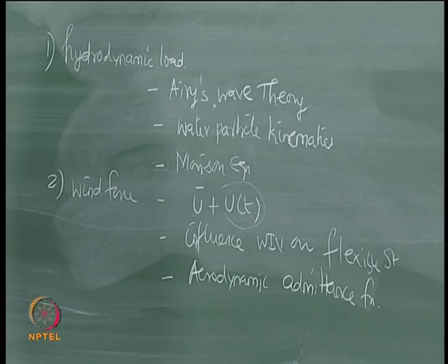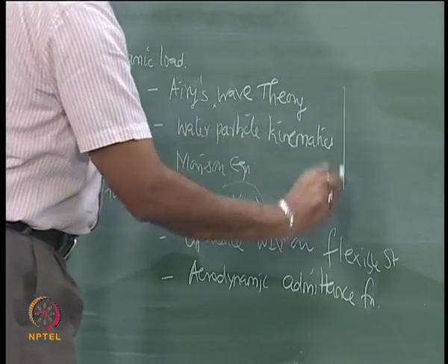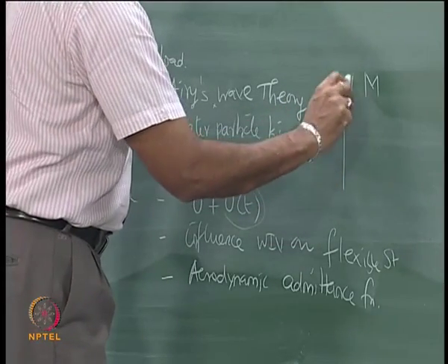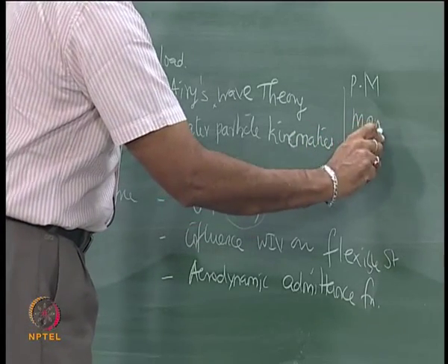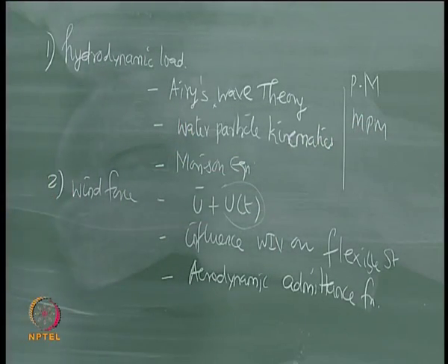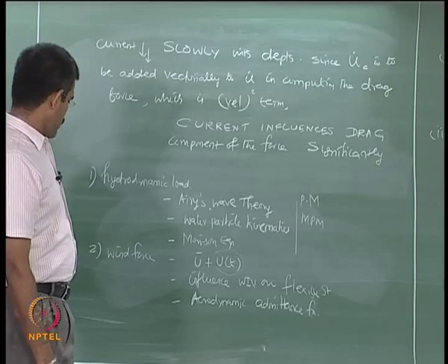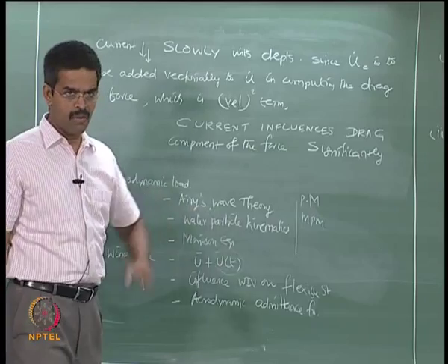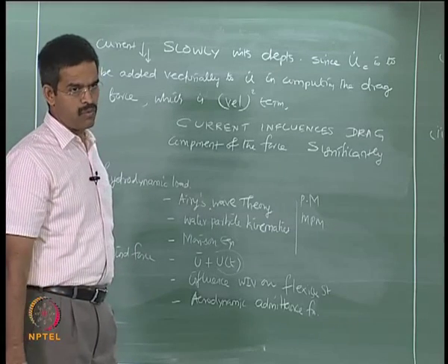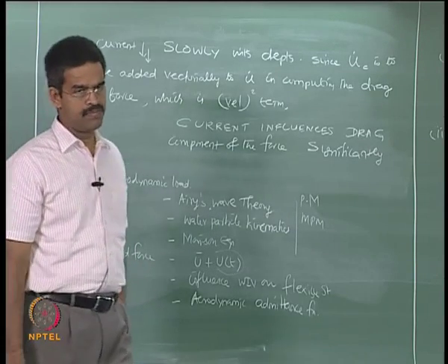Now the question comes, what spectrum should I use for finding the forces? For wave forces we already have the Pierson-Moskowitz spectrum, modified Pierson-Moskowitz spectrum, JONSWAP, etc. Whereas for wind forces, people say I will use the 1/7 power law, but that is generally used for fixed type structures.